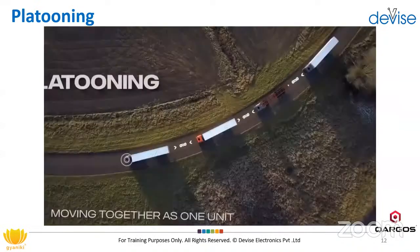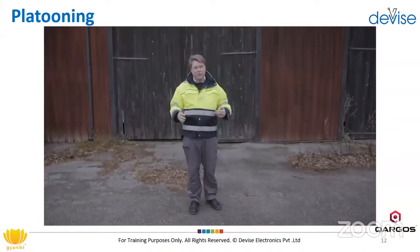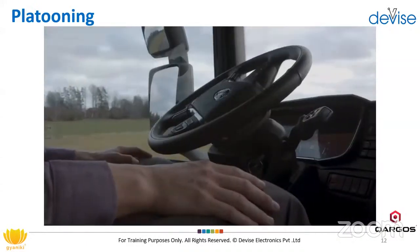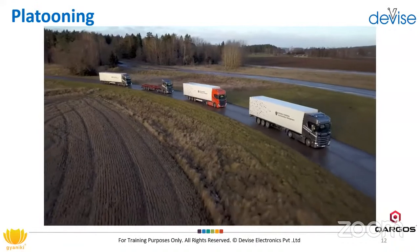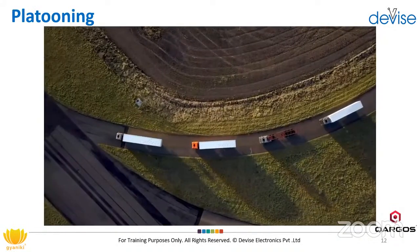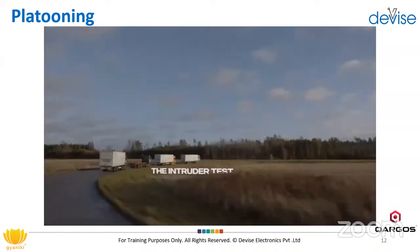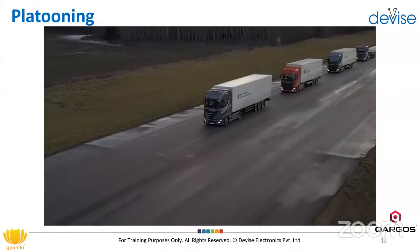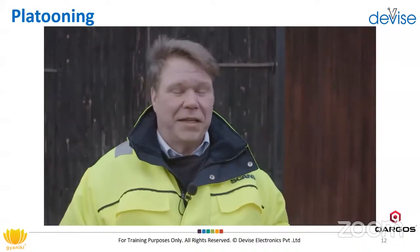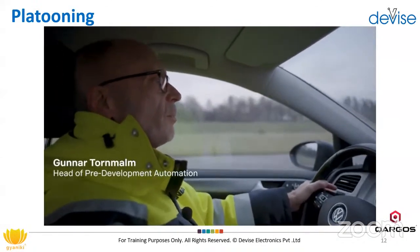When we first began around 2010 driving with the platooning, we only drove with longitudinal control, and today we have a technique that allows us to even let go of the steering wheel and let the truck steer by itself. I was driving as the third or the fourth truck, and it was a great experience. It was very relaxing, giving control to the system, being able to follow 4 vehicles in a platoon without having to do anything. The intruding vehicle, as with today, we're driving with very close distances. We are about 10, 12 meters between the vehicles, so it's very narrow for intruding vehicles to cut in.